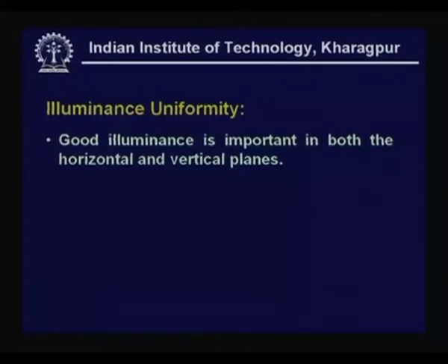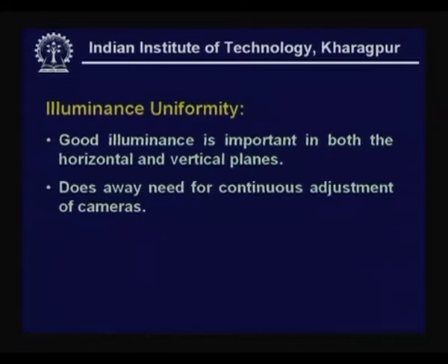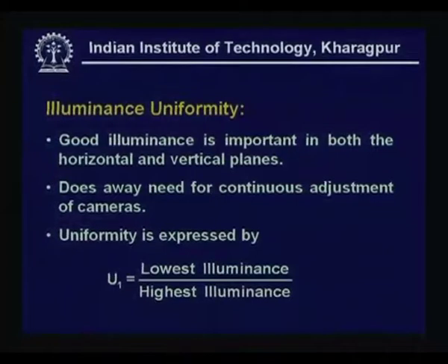Now, good illuminance levels in both horizontal and vertical planes are required, and once you have good levels and uniformity maintained, then there is no need for continuous adjustment of cameras, which is necessary for the media. Now, by definition, we have two indices for uniformity. We talk of uniformity indices for both horizontal illuminance as well as vertical illuminance.